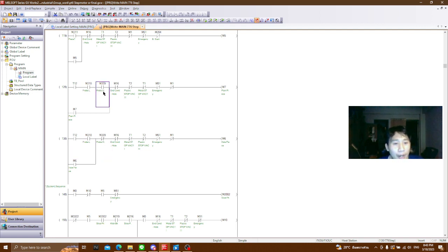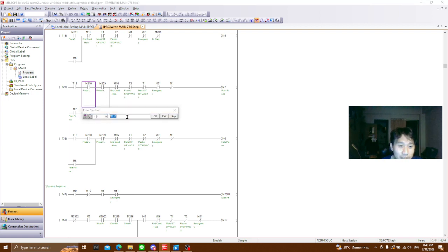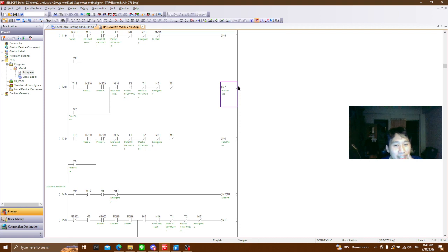So probe low and high. Low and high is like we have two encoders, right? No, we have two sensors. So the probe detects 1 and detects 2 for each level. If it's a plain piece, it will activate both the low and the high sensor. So it will activate both, and then we self-hold it to remember that, M7. If M7 is activated, it will be a plain piece. Same as the piece cutting, we reset the value of this one by the end of the cycle duty, and also the emergency button.